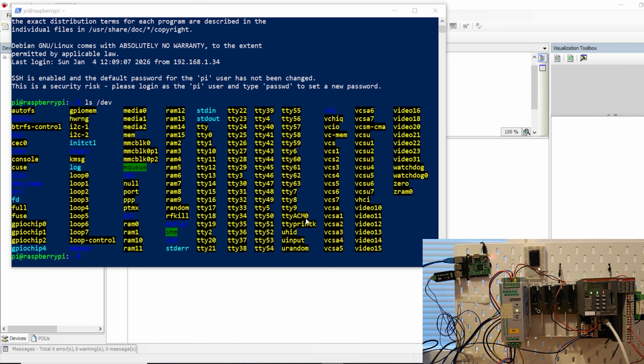So you should see something like ttyACM0 or ttyUSB0, something like that. You can see that the device there is detected as ttyACM0. It's detected on this interface here. So this is the device file representing our converter here. We can access our converter via this device file, as you can see. So it's ttyACM0.